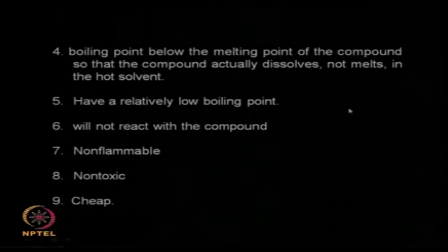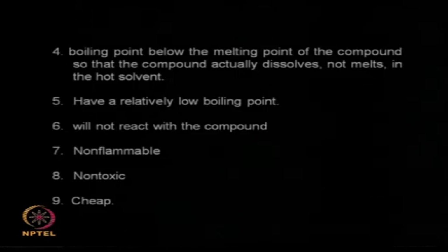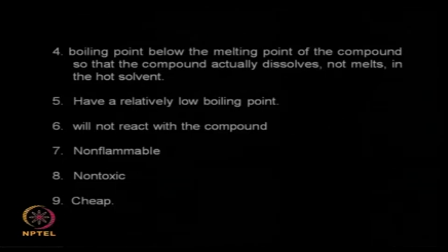We do not want the boiling point to be very high, then what happens, you may have to resort to high energy expenditure. It should not react with the compound, that is also very important. Otherwise if it starts reacting, then you will not be able to do the crystallization process. It should be non-flammable, that is very important, that is from the safety point of view. It should be not toxic, because when it is in an industrial scale it should not affect the operators, and it should be cheap.